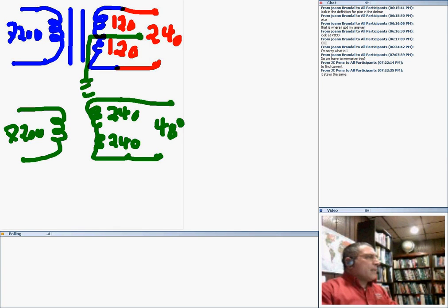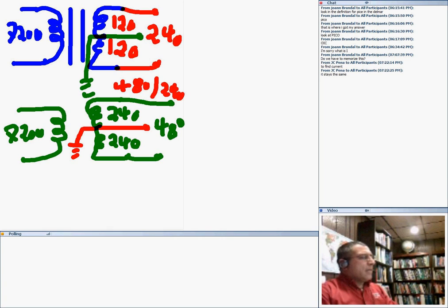Okay. Then my friend Joe said, Chad, I need another voltage. Could you please bring me another voltage? Okay, no problem. I'm going to ground this as neutral. And now this voltage is a 480/240 single-phase system. It does not exist as three-phase, but I can create a 480/240 single-phase system.